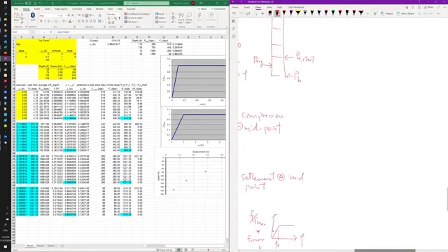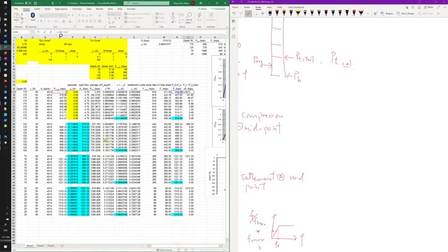So at the beginning we assume this, right? Now you have another one that you calculate at the end, and you will compare these two numbers. That's what we do. So at the end of the day, we compare these two numbers, the one that you assume at the beginning and the one that you calculate. Make use of the TZ and QZ curve, and also elastic compressions. And also along the way, you find all the settlements. Because of the TZ and QZ response, and also the elastic modulus you have at the beginning, you can recover all the information, which is all the loadings and all the settlements.